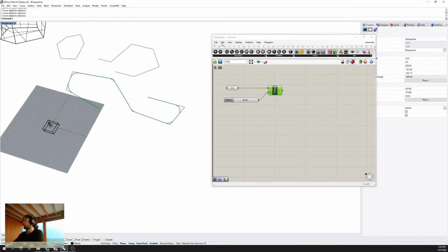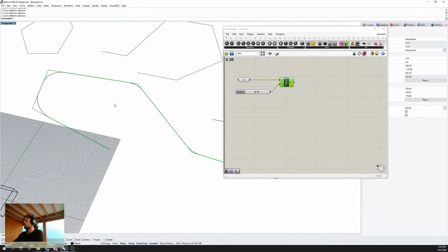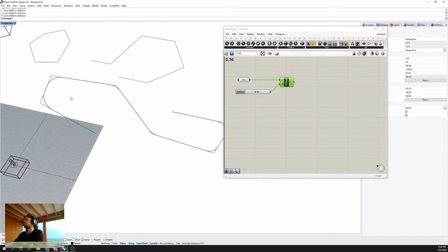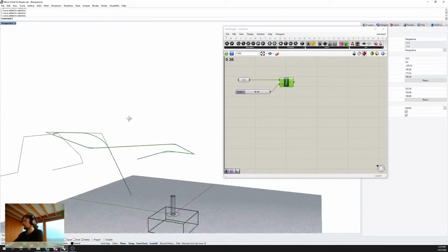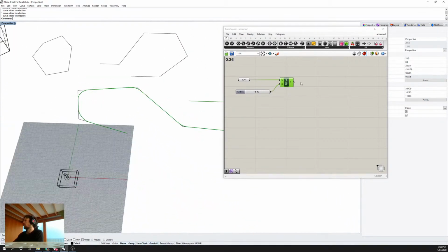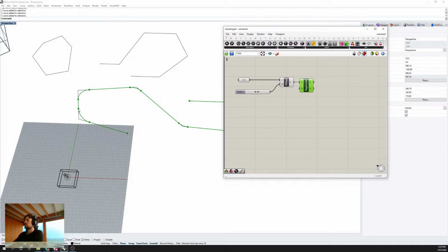And so this, as Sean would have shown you before with the filleting of those curves, this actually shows you what the part is more likely to look like after it's been bent, because the bender typically introduces a fillet into each one of the parts. So we get this filleted version of the curve, and then we can explode this curve to get the individual segments. So we end up with straight line segments and fillets, right? Which is kind of nice.